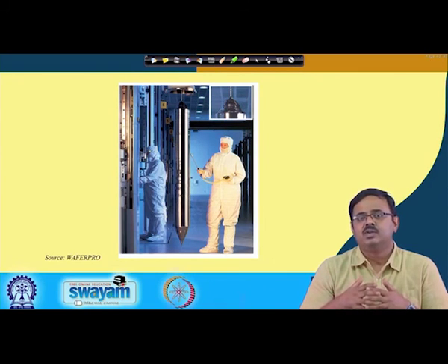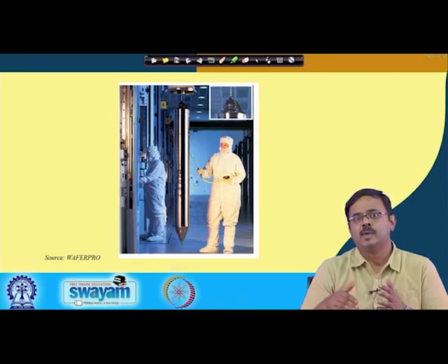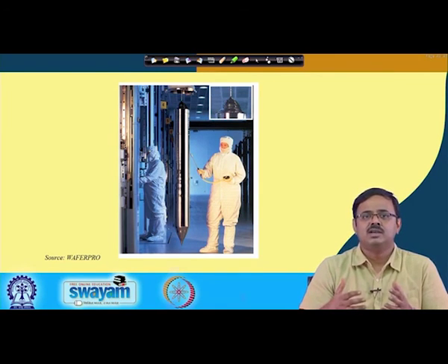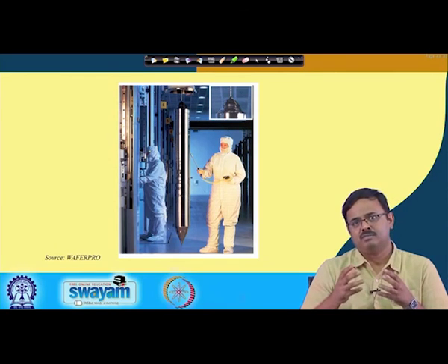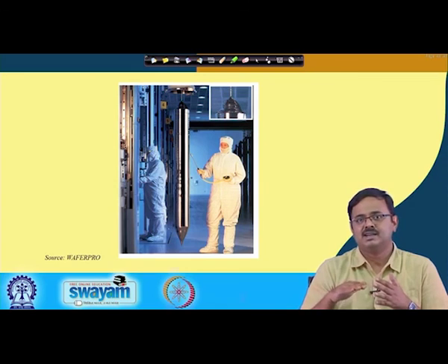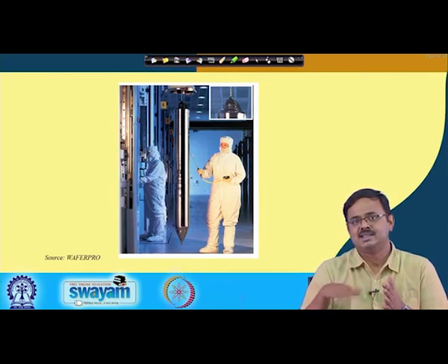And then we looked at the various levels of packaging, and the first one was to generate this die from a wafer. To start with, you have to go back and find out how a wafer is made, and that led us to the discussion on the Czochralski process, by which a silicon ingot is grown from pure or precisely doped silicon. Then you slice the ingot to give rise to these wafers, and from the wafer you further dice it using laser cutting to give rise to these individual dies.